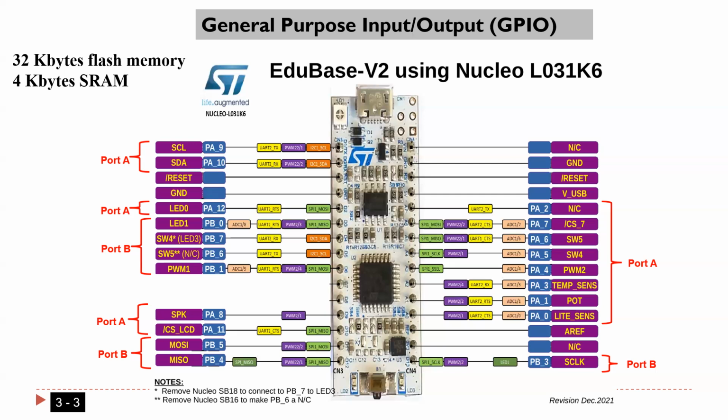So I told you we have several ports here. I told you the purpose of this chapter is to learn how you can program input-output devices. I started last time with LEDs. I'm going to continue teaching how you can use the buzzer, the LCD, the keypad, the 7-segment as well, and other input-output devices. I told you guys any input-output device has to be physically connected here to this one. Is that okay? And last time we used LED 0.